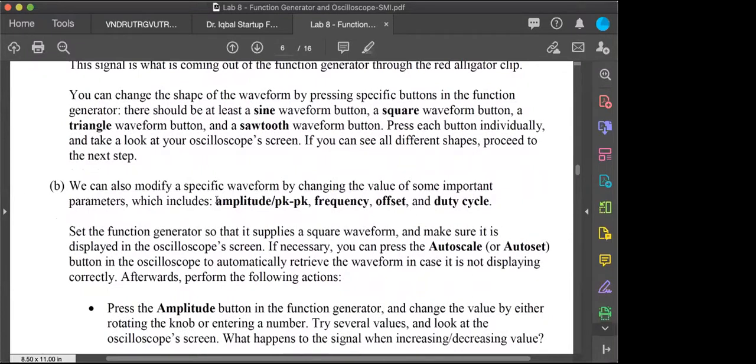And then there are also options where they ask what kind of amplitude you are inputting: amplitude, or peak to peak? So you tell the system what you want, exactly the same way I showed you on the website. Then you set the frequency, and you see the offset, how far up on the X or Y axis you want it to be. You want to align it basically to the gradings given on the screen.